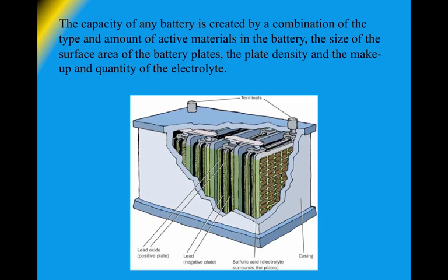In deep cycle lead acid batteries, you see lead plates and lead oxide plates that have a much higher density than in automotive starting batteries. And the reason for that is that automotive starting batteries use a spongy form of lead that provides greater contact with the sulfuric acid electrolyte, allowing the battery to put out a great deal of amperage all at once to start your cranking motor. But it has a decent lifespan because it is immediately recharged.